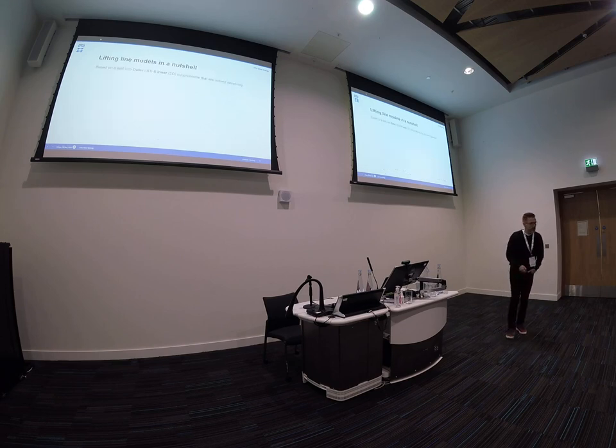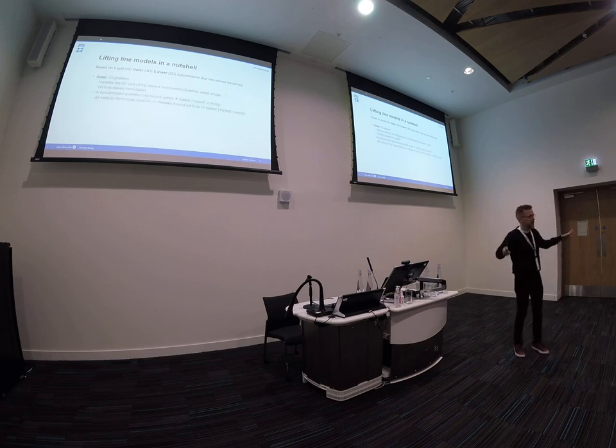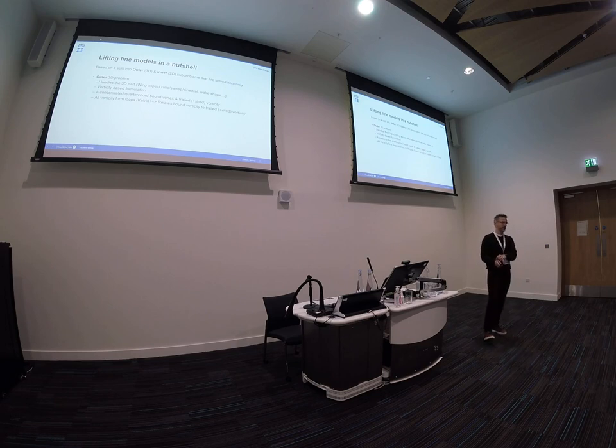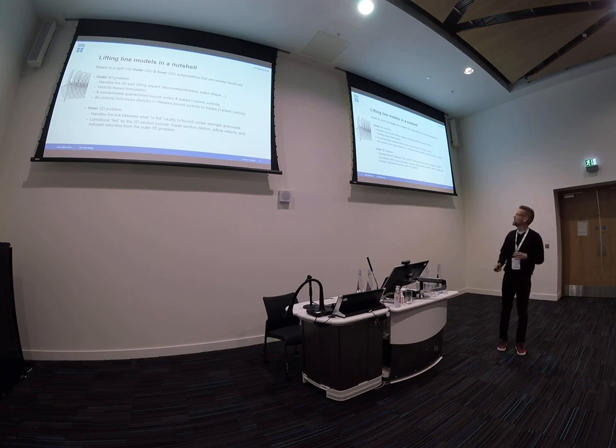So you split the problem into an inner problem and an outer problem. The outer problem is the 3D system. If you go very far from, let's say, a wind turbine, it is like 3 sticks with forces on, that's the wings. And you can think of a grid of the wake behind, which could look something like this. Then the inner problem is the 2D section, where you look at it and have a leading edge, trailing edge, and pressures on that. And then we split these sides, or these domains.